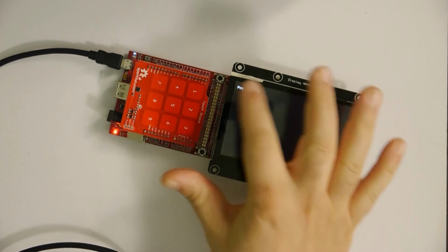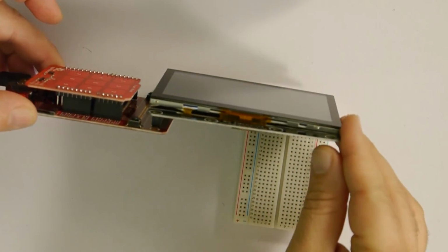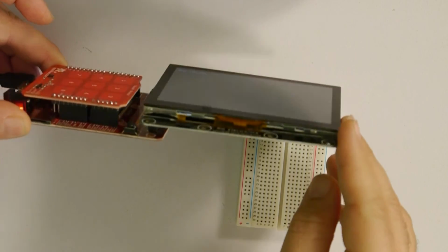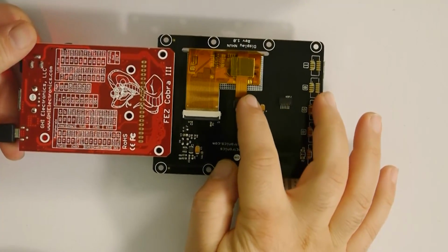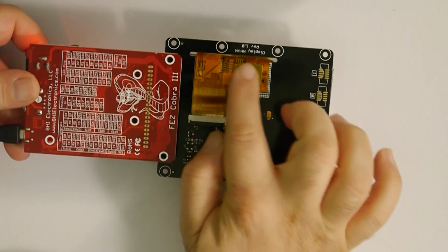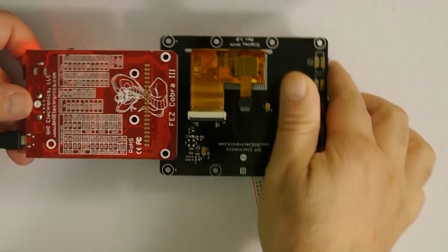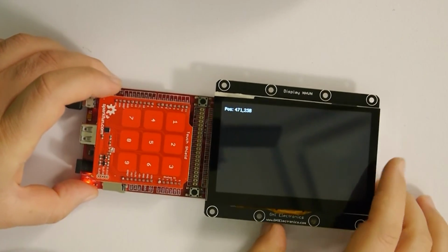So the screen that sits on top, this is not the LCD. So keep that in mind when you look at LCDs. The touch on top might be connected to the same cable on the bottom, so you have one cable. But if you look at the side, on your display, you would see that they are separate. So in this display, they are separate. So this is the cable that goes to the capacitive screen. And over here, where the square is, there is a very tiny circuit that has a chip similar to this one that is handling the touch.